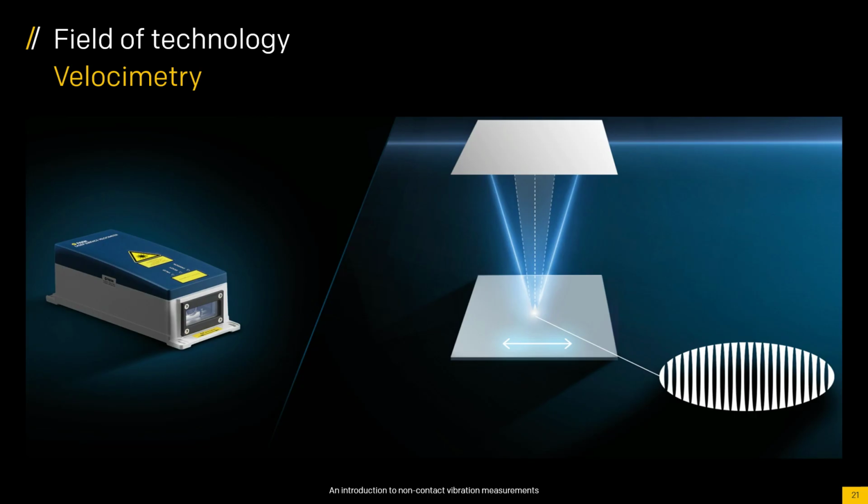A couple of things to keep in mind. Number one, frequency of interest. Anytime you mount a vibrometer on a tripod or suspend it somewhere, those are super low frequencies. We are talking sub 2, 3, 5 hertz. It cannot move much faster than that. So it depends on the frequency of interest, right?